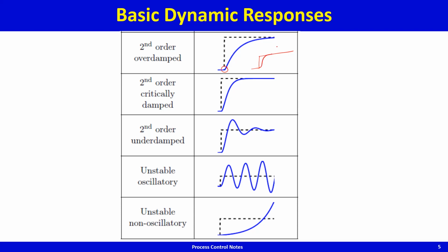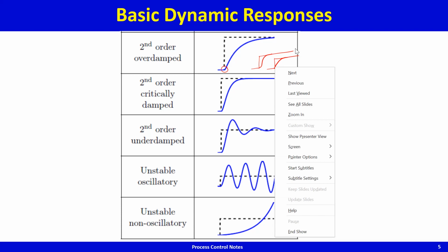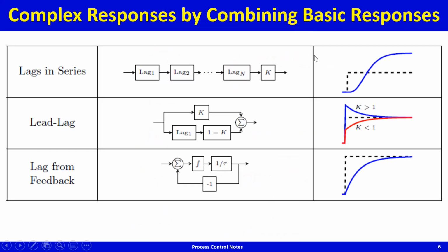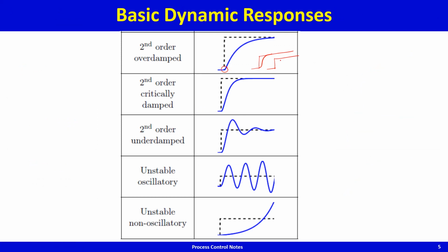On the other hand, in a first order response, the rise will be immediate. You give the time, it will be like this. So the rate of change at time t equal to 0 in a first order lag is finite. The rate of change in a second order overdamped response at time t equal to 0 is 0. So you have a S-shape-ish response. That's the difference.